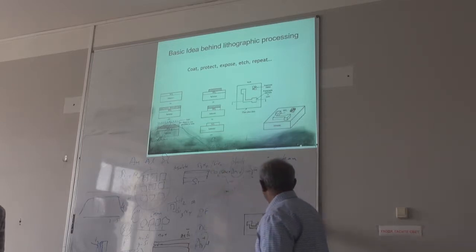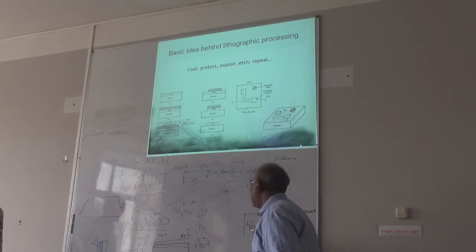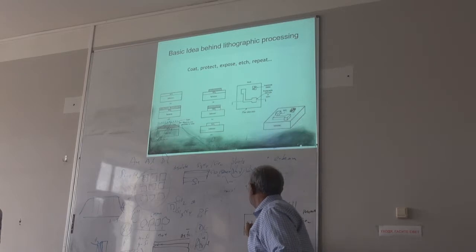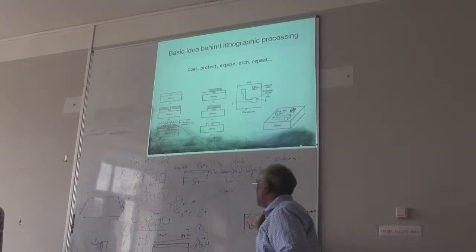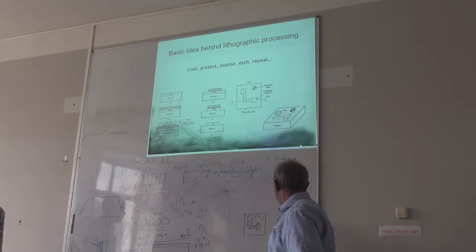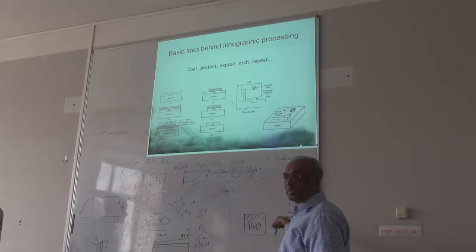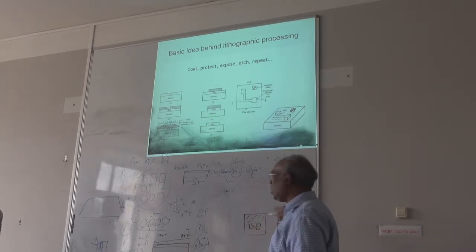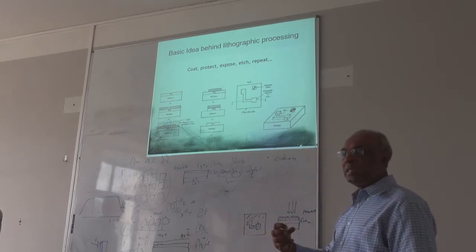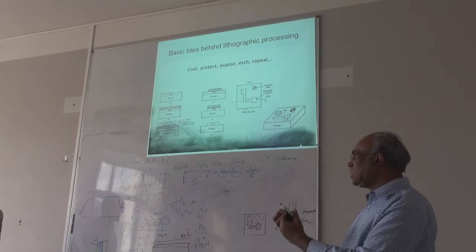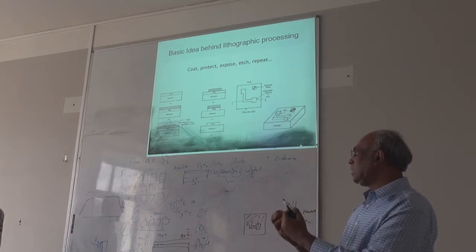So now, when you put here, this is that opening here. When you expose to light, only this part gets exposed, because this is all closed. Then this polymer has some special property. When you expose to light, the polymer becomes, we call this cross-linking.